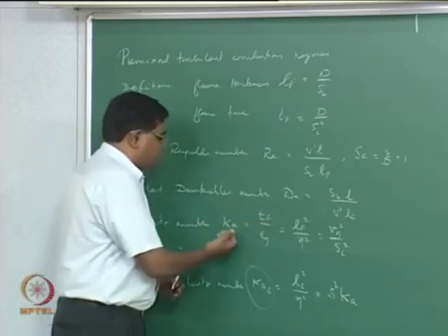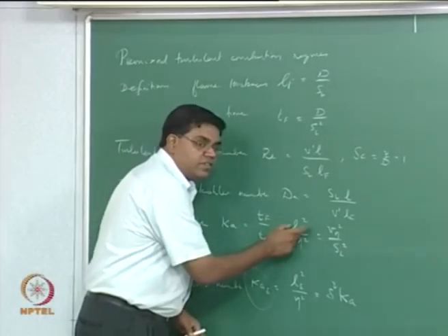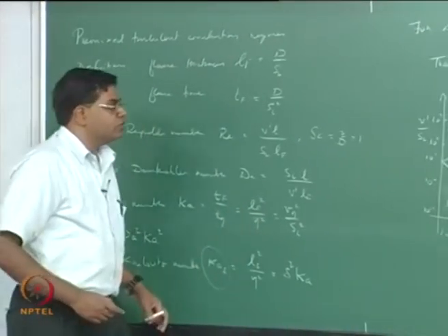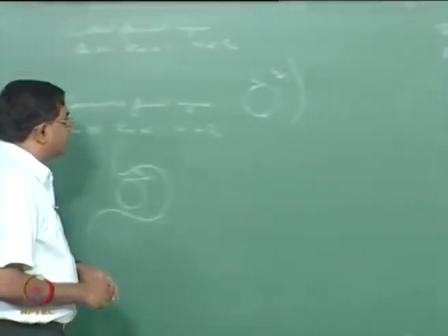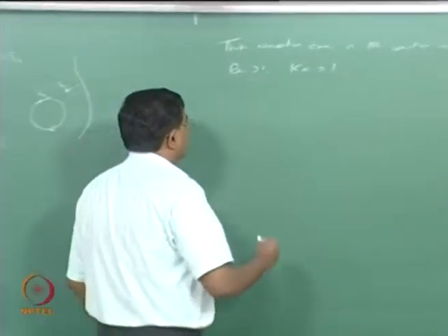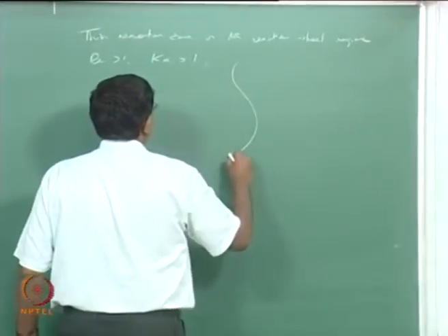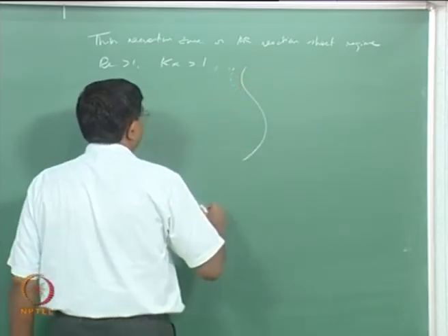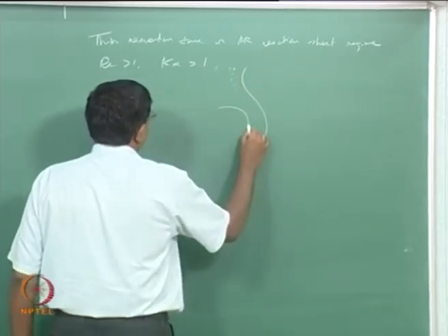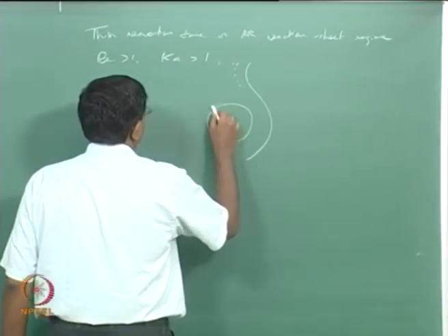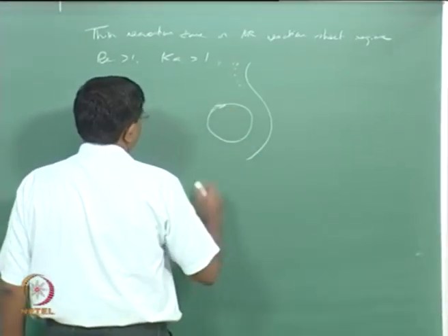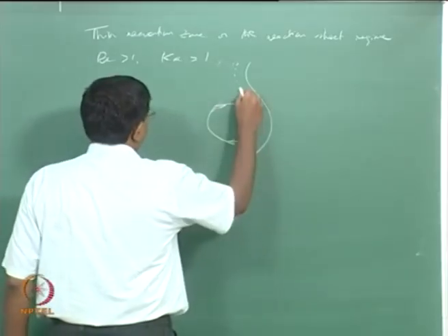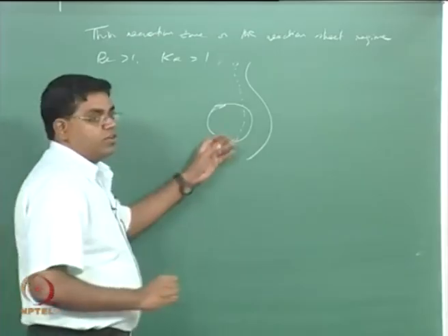If Karlovitz is greater than 1, then the flame thickness is now getting to be bigger than the turbulent scales, right. So what that really means is you're now going to have a flame that is having a preheat zone starting out like that, but you now have an eddy that is big enough to penetrate the preheat zone, and then the preheat zone thickens.